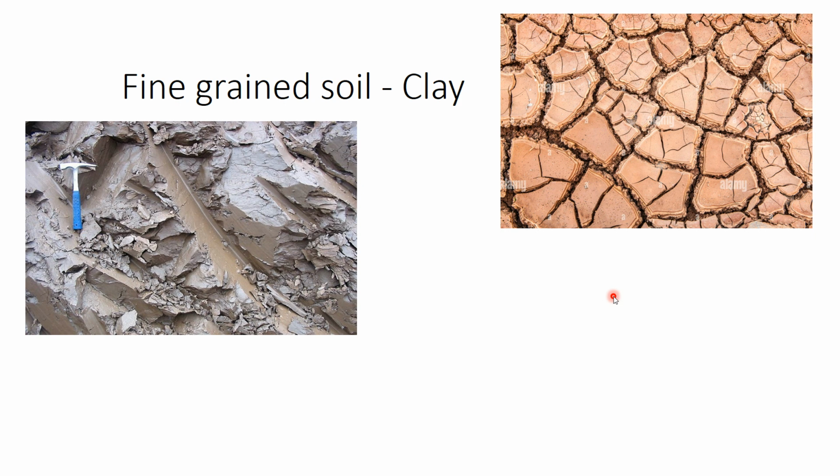You know that from rock only we are getting the soil. Over millions of years it has undergone weathering. So it is a chemically weathered product. In day to day life we have seen that clay was used in our agricultural fields. Okay, why? Because it has good moisture holding capacity, so that your plants can grow well. But when it comes to foundation, when it holds moisture, it is not very good for the foundation.